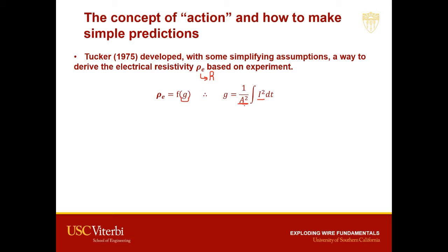Because as the wire expands and undergoes melting, afterwards vaporization, and plasma expansion, we know that the cross-sectional area of the wire is bound to increase. Here he is considering the area constant, which also means he is basically linking these variables, and although the area is increasing, the overall effect is inside this resistivity. So let's take the area out of the integral and consider it constant and equal to the initial area at the beginning of the explosion.